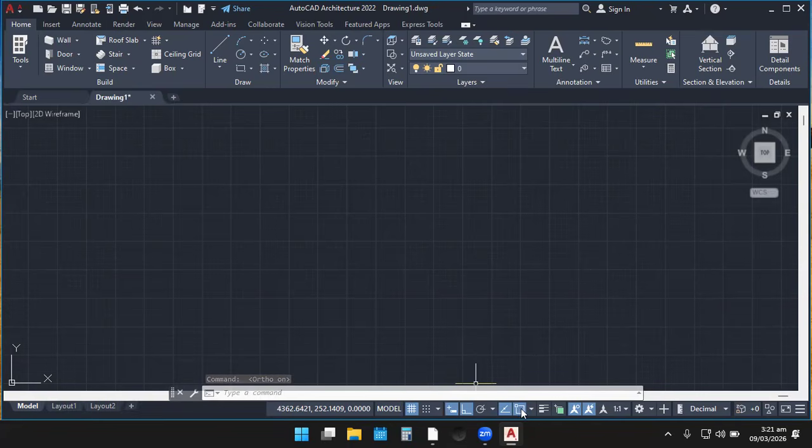This over here is called the snap cursor. Or let me say, it's called the object snap. The object snap can also be activated with F3. So it is actually on, and when I click it again, you realize that it is off. When I click it again, it is on now. So let's test the other one.